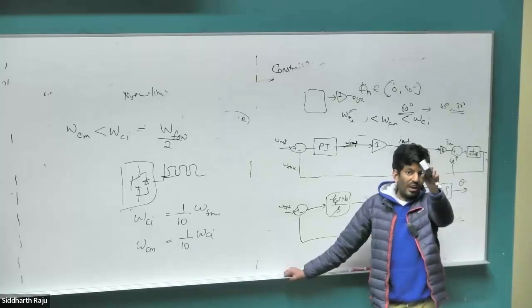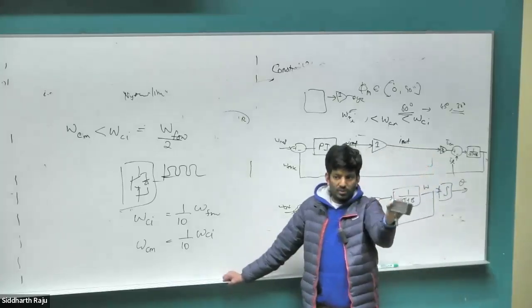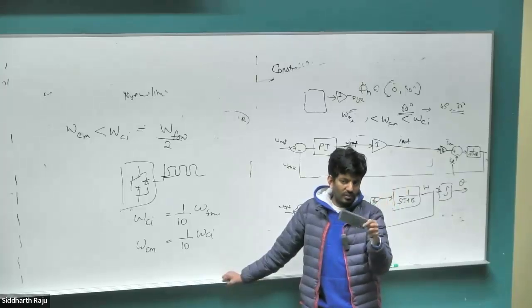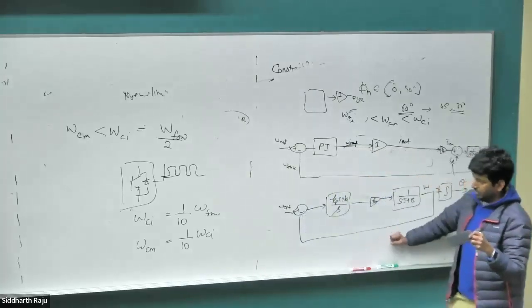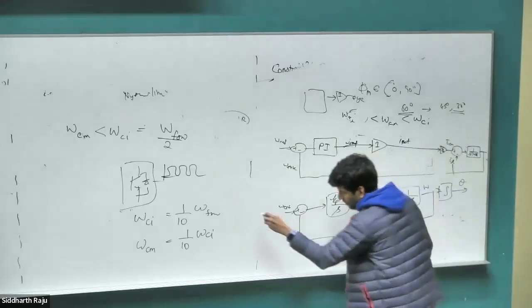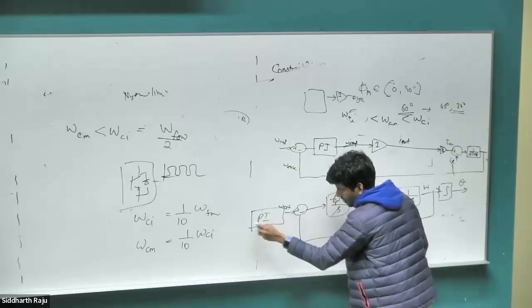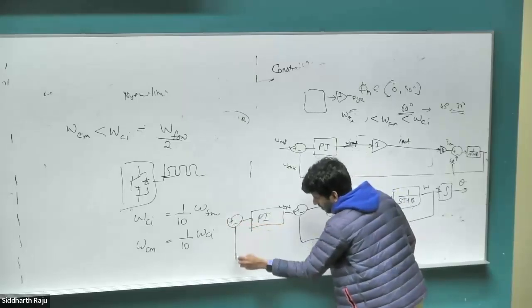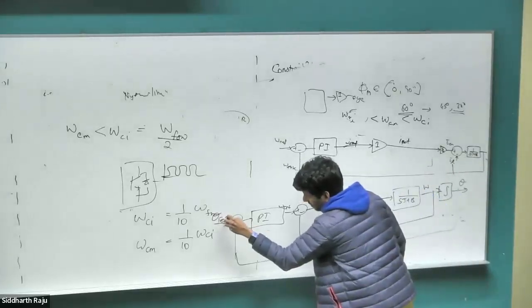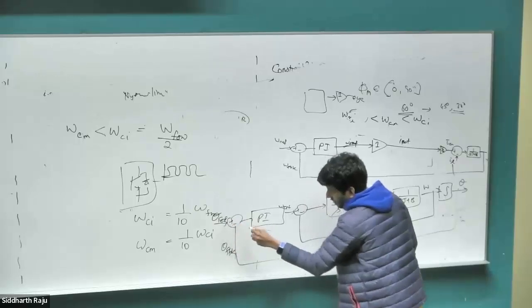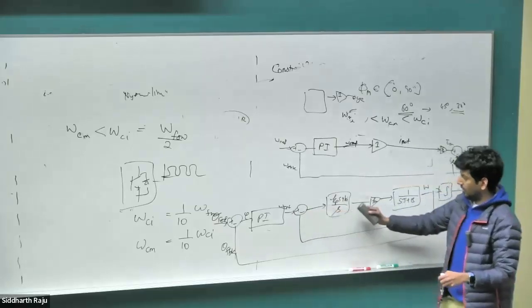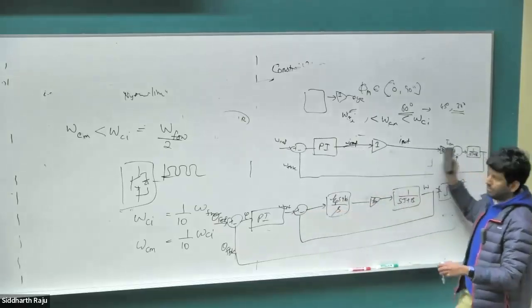The camera that we have right there is basically controlling the angle of the motor. You could typically have a DC motor, a real DC motor in that case, and you're basically controlling the angle. So how do you control the angle? You can just cascade one more PI controller. So close this loop: theta reference, theta feedback, and you get the error. This error is going to go to a PI controller, and that is going to control the speed. That in turn is going to control the current, and that in turn is going to control the whole thing.